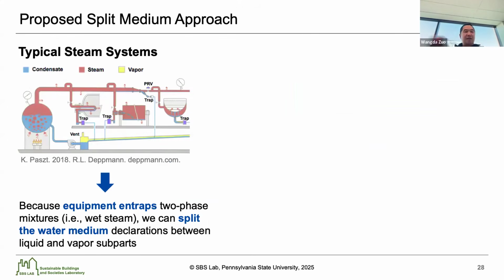Then the idea is, let's look at what's happening in our actual steam systems. This graph shows, very simply, the boiler. So that's the phase changing process, right? You feed the liquid water into the boiler. Now you get high pressure steam. Then you can use a pressure reducer valve to provide low pressure steam to the network. And then you have condensation going back, then connect them, feed into systems.